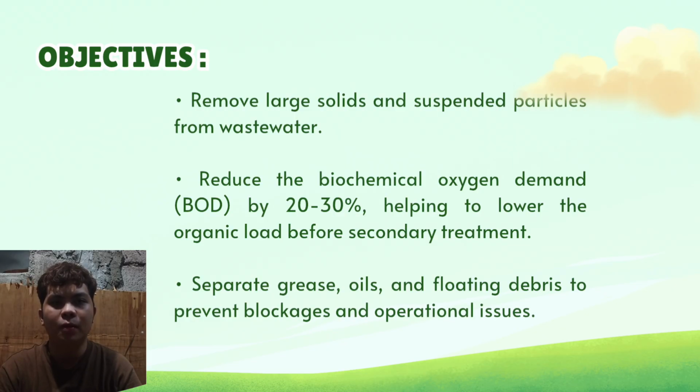Number 2, reduce the biochemical oxygen demand or BOD by 20 to 30%, helping to lower the organic load before secondary treatment. BOD is a measure of how much oxygen microorganisms need to break down organic matter in wastewater. If too much organic material remains, it can deplete oxygen in natural water bodies and harm aquatic life.